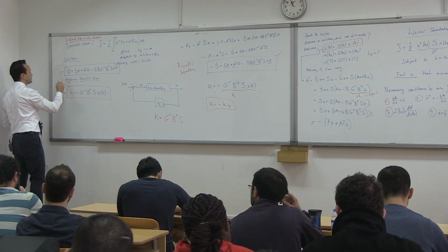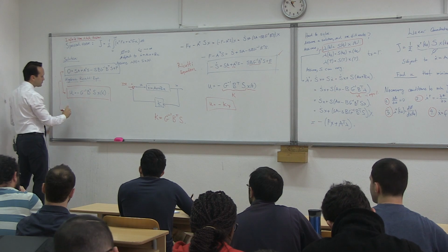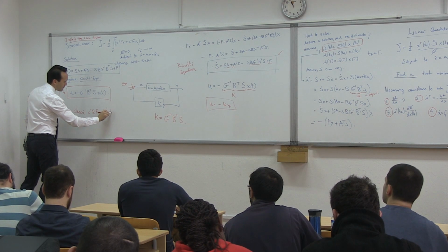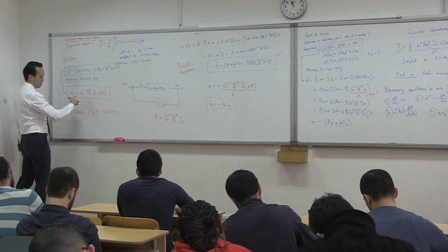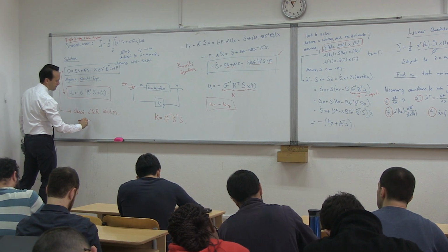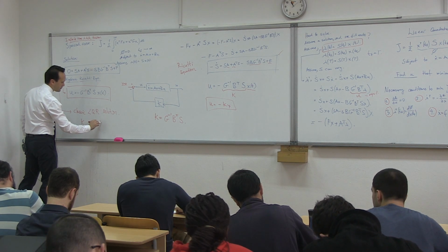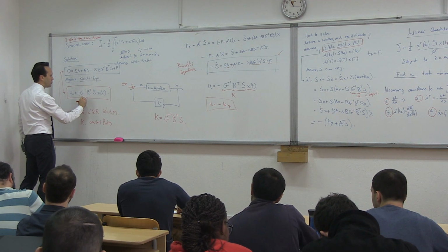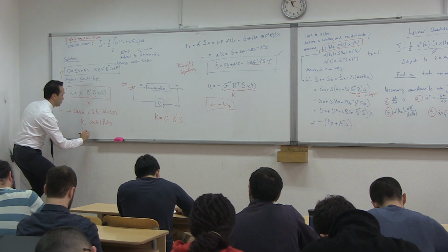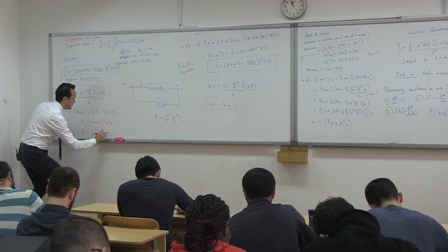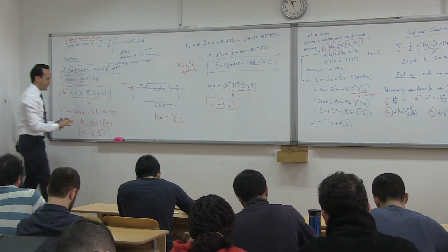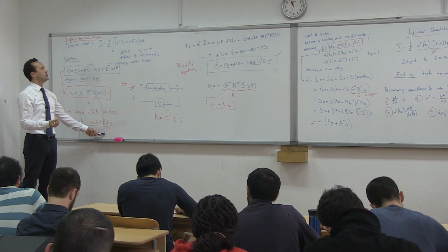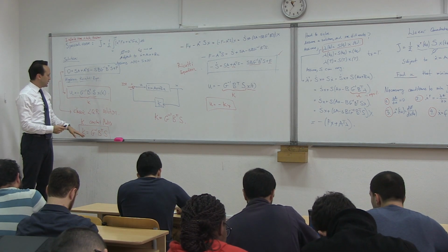And what you're seeing here is a classic LQR solution. Okay? So K will be a constant matrix, where this part here, of course, is K. So K is equal to G^{-1} B^T times S. Although S is not in the problem anymore, it's a variable called S that still appears in the solution.